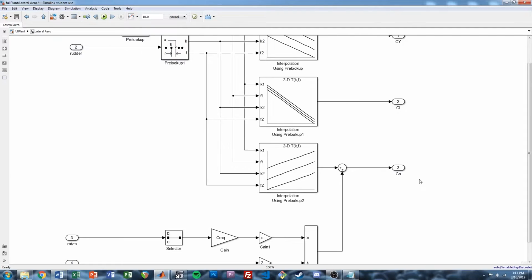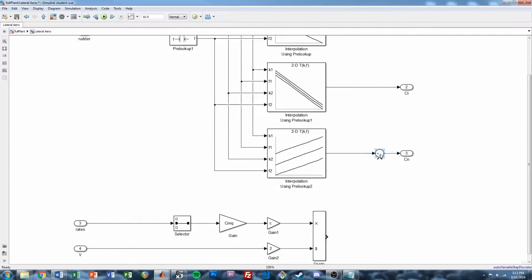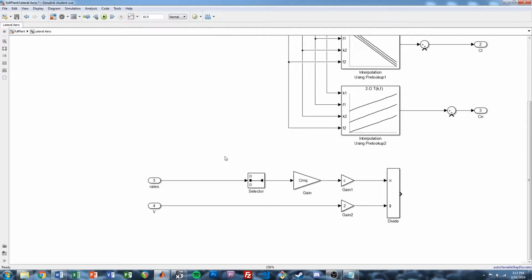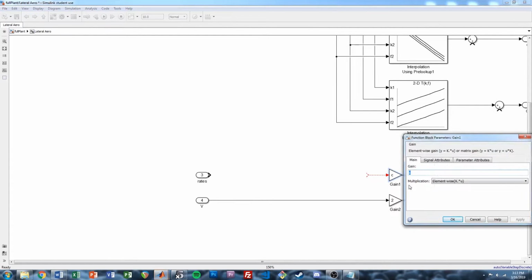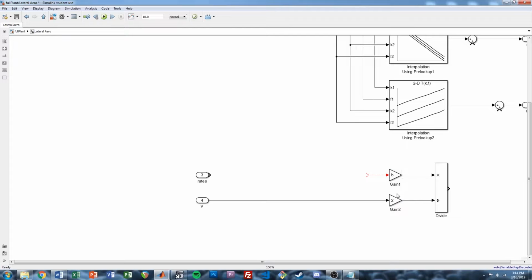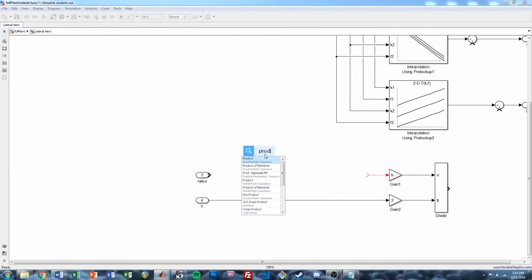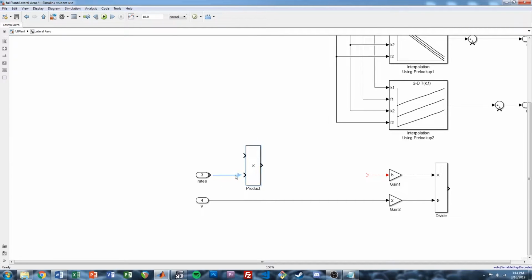Now, our damping is going to be a little bit more complicated this time. So I'm going to go ahead and get rid of this, scoot this over here, and then add another sum block up here. So we're going to add in both the rolling moment and yawing moment contributions from our damping. So instead of just selecting Q, I'm going to make a matrix that has our derivatives. I'm going to take that matrix, multiply it by our angular rate vector, and then use that to generate the rolling and yawing contributions. So let's get rid of this. Get rid of that. These are going to be B now. So instead of non-dimensionalizing by the chord, it's going to be non-dimensionalized by the span, since these are the lateral terms. Keep the 2. So we'll have B over 2V. That's going to be our non-dimensional roll rate and yaw rate. So let's do a product. This needs to be a matrix multiply now.